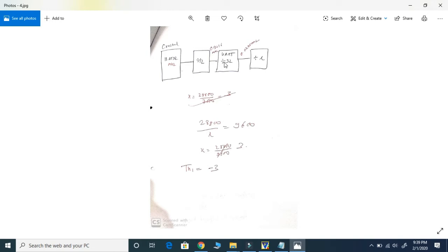0.9216 megahertz divided by 32, we will get 0.0288 megahertz. Okay, this is in megahertz. And then we have to divide this by X, and we know that the baud rate is 9600 bps, so we have to convert this megahertz into bps. It will become 28800. So we have to find this value X, then we will get 3.